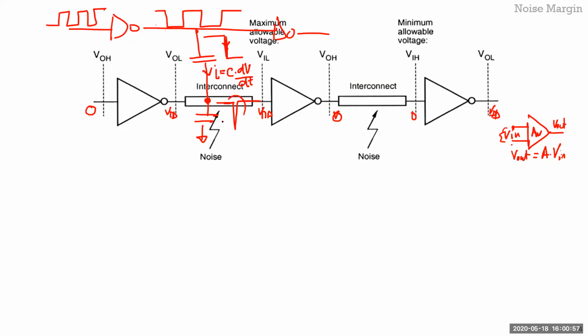Now, obviously during this glitch, or if there is just power supply noise, you don't want this output to respond to it in the same fashion or have a positive glitch like that. Your output should be sitting at 0 because that's not a signal, it's just noise. And that's the whole idea of noise margin: in real circuits, everything is banging around.